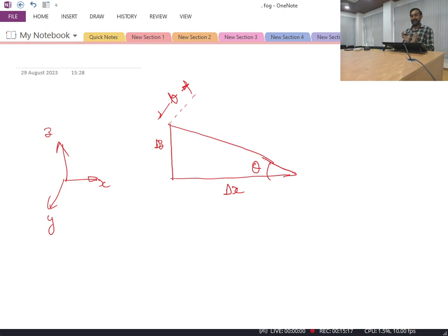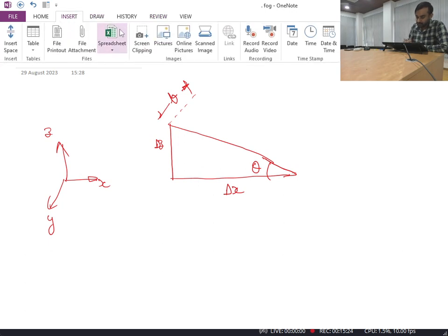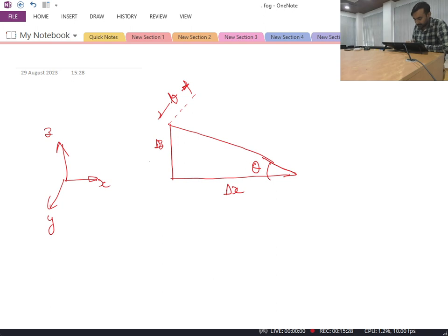Let us consider that this fluid element at rest is subjected to some pressure. So of course it will be subjected to the pressure force, whatever force is acting because of the pressure. So let us consider that in this direction first it is having pressure Px, and in this direction it is subjected to pressure Pz, and normal to this interface I am writing the value of pressure as Pn. Okay. Now let us consider that the density of the fluid which we have considered over here is rho.